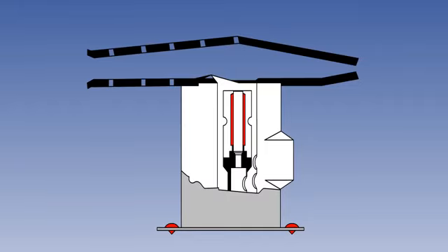Let us look at how it works. It can be seen that some of the air entering the probe is turned at right angles to pass over the sensing element. This is to separate the air to be sensed from any water or solid particles present. Flow separation is achieved because water or solid particles have sufficient kinetic energy to pass directly through the air intake and exit. The bleed holes we can see in the intake casing allow the higher pressure air escaping from within the intake casing to draw off boundary layer air.